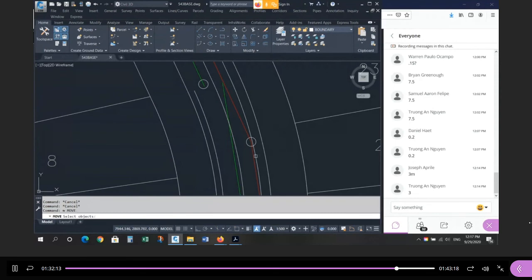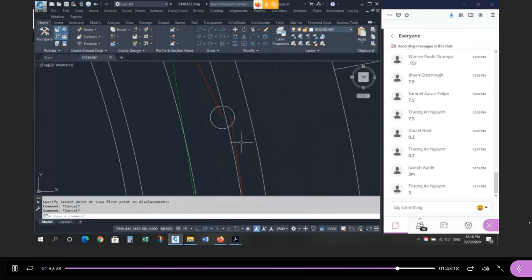Now, there's more than one solution here, right? I can push this further, right? I can go this way, but not any further. Now I'm encroaching on that 1 meter no touch zone. And if I go the other way, eventually I'll be in the no touch zone here. Right? If I extend to here, now the center of the maintenance hole is too close to the edge of asphalt, has to be at least 1.5 meters away.